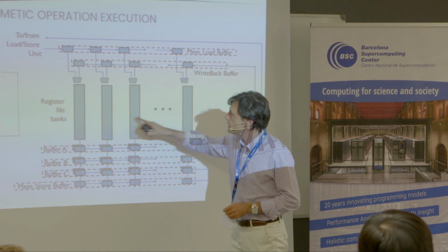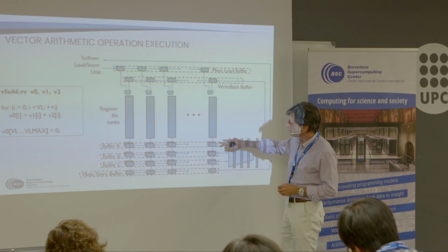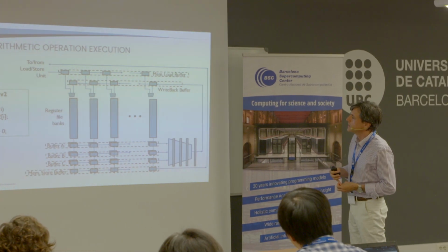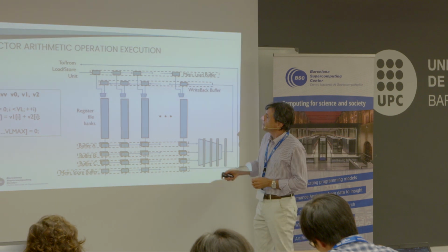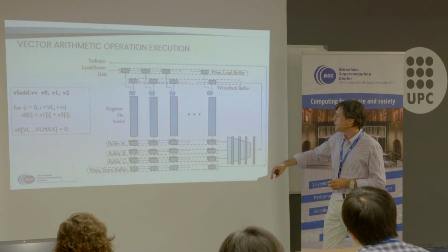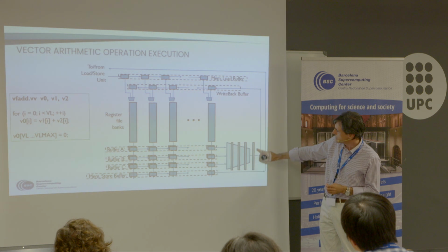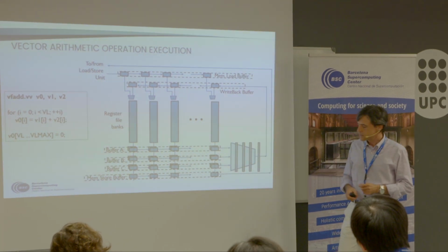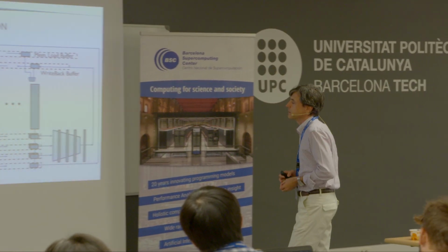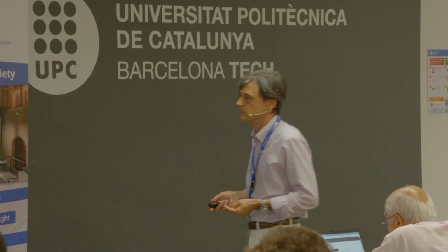So you have these register file banks, and you see 3 buffers here. Actually, the buffers are all double buffers. There is a reason for that. It is not now the case for discussing that. These buffers, A, B, and C, contain the input operands for the functional unit that is represented by this part on this side that is actually doing the real operation. So basically, this is a floating point unit, in particular capable of doing fused multiply-add operations.